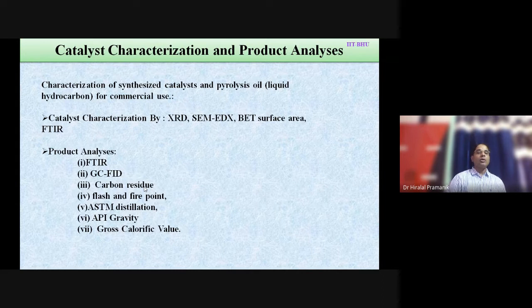So it talks about the propensity of cracking. If you have a fuel oil consisting of higher molecular weight hydrocarbons as well as aromatics with long chain paraffin, that has a tendency to break down, and then it will finally form a giant molecular structure of aromatic hydrocarbon, which will appear as carbon black and deposit in the engine. So if the percentage is greater than 1%, then we do not recommend. So the carbon residue test is a very important test method to find out the suitability of use of fuel in IC engines.